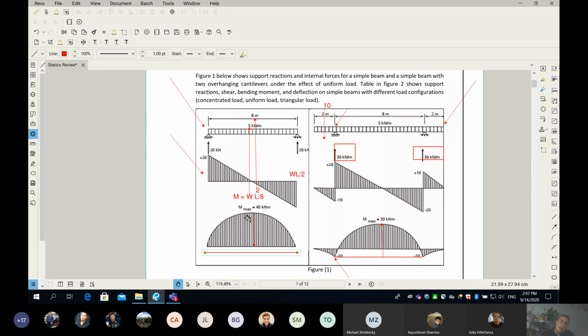You can see, look at the parabola. The bending moment dies as you go to the support. It means the moment here is 40, probably here is 30, 25, 20, 10, 0. So again, hopefully you get the answer. If you don't really want to save any amount of money on material, then you take the maximum bending moment, you design for the maximum, and then you simply use the rebar all the way across your beam. However, if you wish to do some saving, when the moment applied to the beam is reduced, then in this case, maybe you will also reduce the rebar.